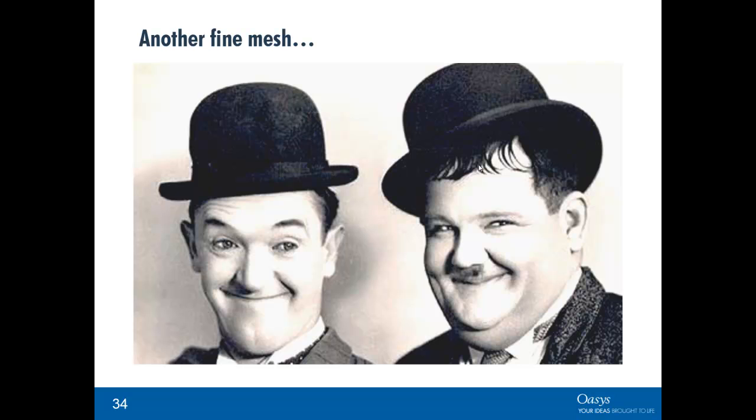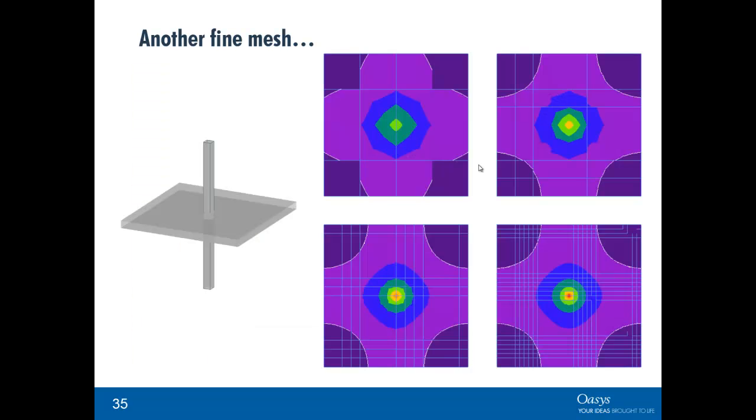Meshing 2D elements. Shape and size and so on is important to the mesh. Now, let's look at this flat slab example. Four images on the right, gradually increasing the mesh density. And you can see the top left with the crudest mesh, we're getting quite large gaps in the contours. It's insufficiently fine. We increase the mesh density, we're getting better contours. But you also note the moment in the middle over the support is also increasing.